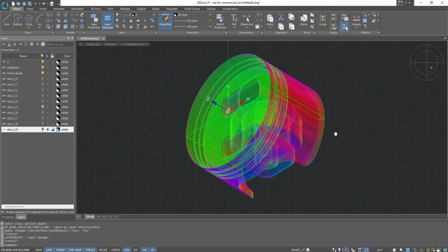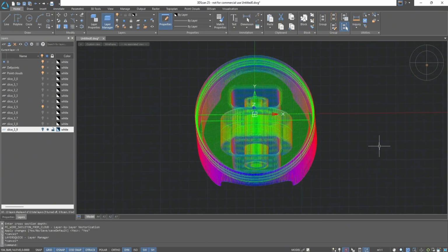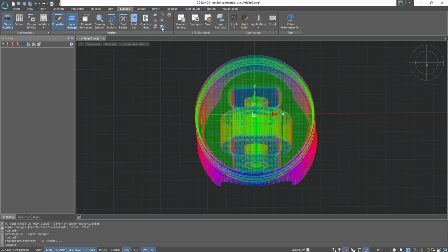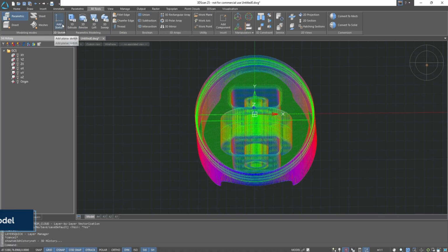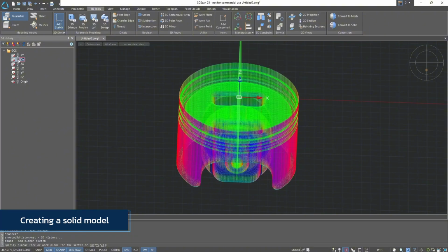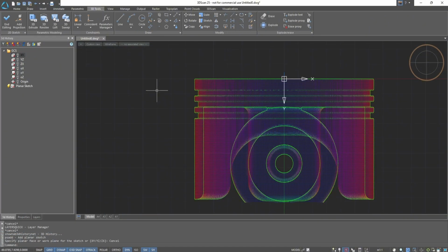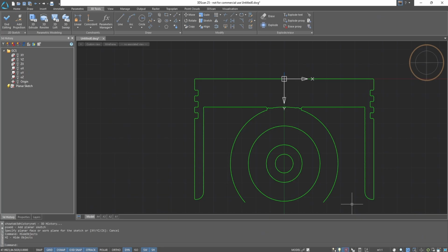At the moment, it is important for us to create a contour that will circumscribe our piston and will be a general-purpose primitive without additional details. So we will now begin to create our sketch. Turn on 3D History. Let's draw a general outline based on the created polylines. I suggest hiding the point cloud for convenience.